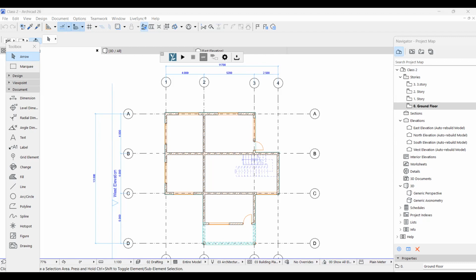And the strength of steel, concrete, you can change if you want to change. If you are using another code, you can change. You can also change the cover for reinforcement. Given for slab is 20, beam 25, all that. If you are using another code, you can change so that it can coincide with that code. So you cancel those. I don't want to apply any change.